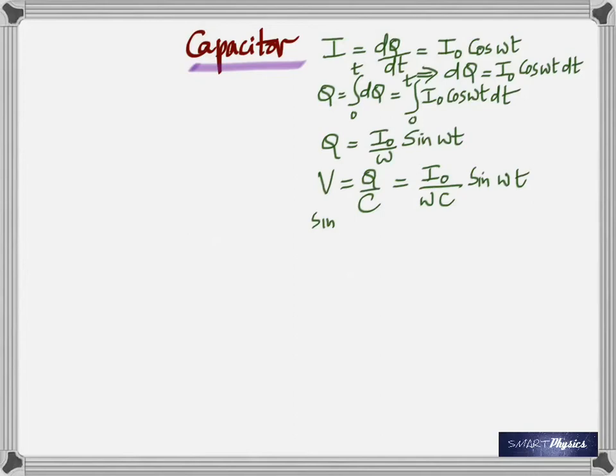Now, what do you see again? Again, we started out saying current is a cos function. What did you end up with? A sine function. That means again the voltage and current are out of phase. How many degrees? 90 degrees. But we need to find out which one is leading. All right, this time sine theta can be written as cos 90 minus theta. So, now that's a trick, you could have written the other way too.